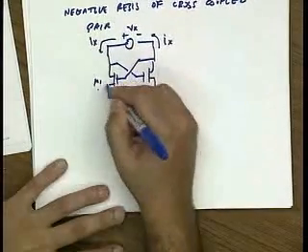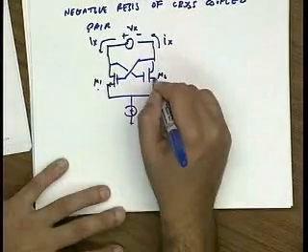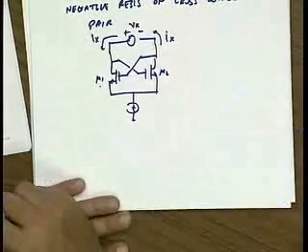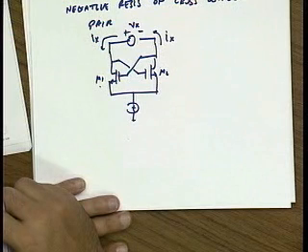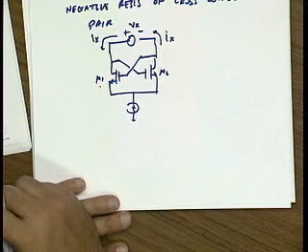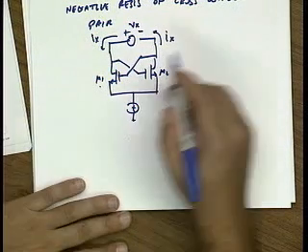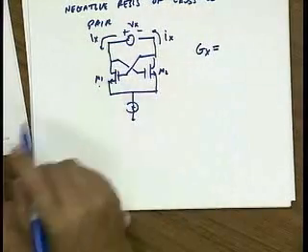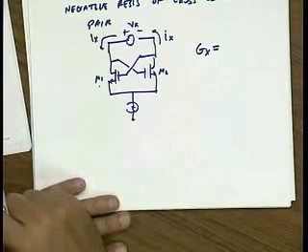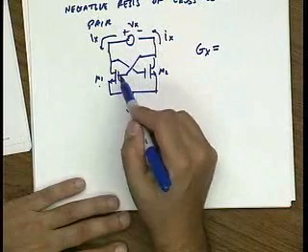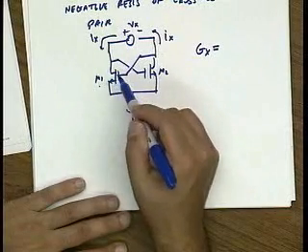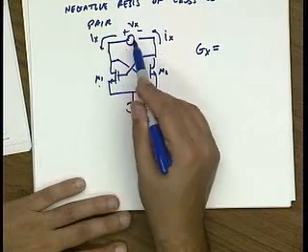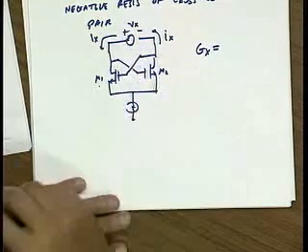Okay, let's call this M1, M2, and this is the NMOS version. Equivalently, I can analyze the PMOS version. Well, you can see this is actually a very simple circuit. The negative conductance connected across here, if I neglect the capacitances in this device, the current flowing through this device is just the GM of the transistor times half of Vx, because it's a differential circuit.